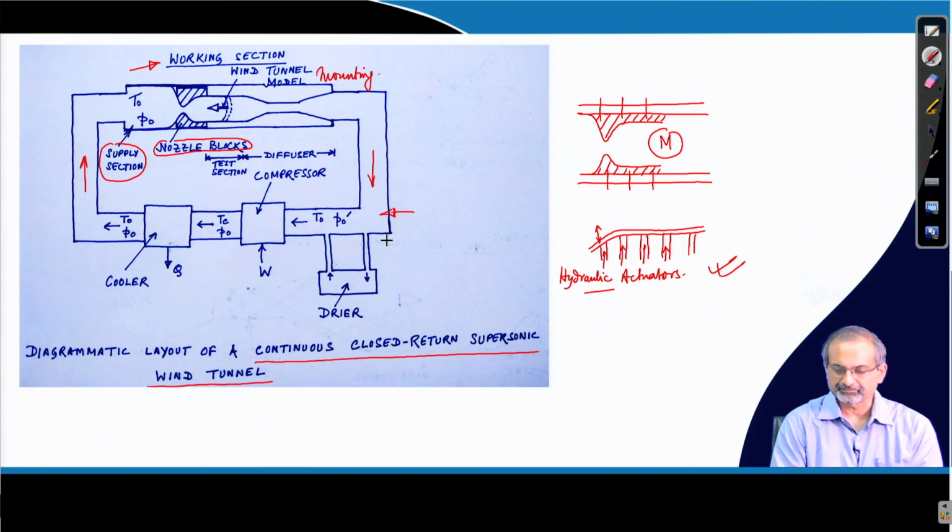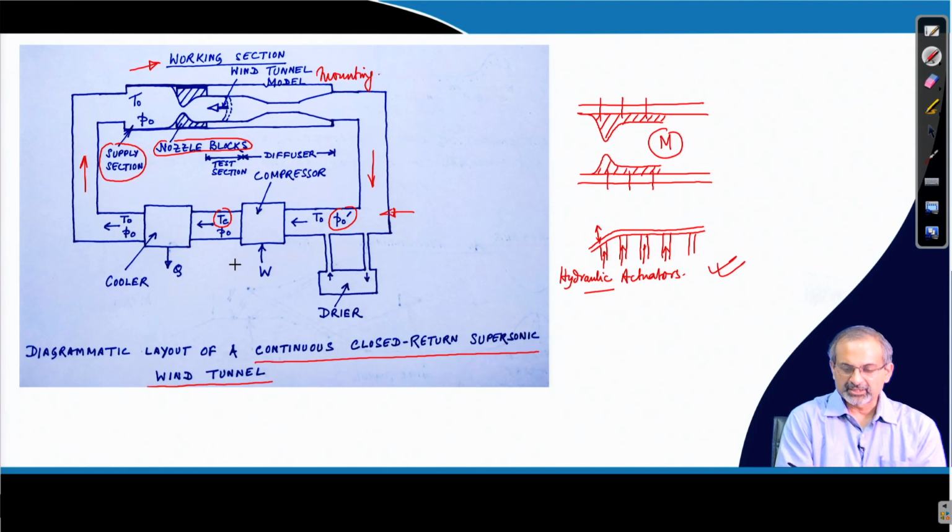And then you can see that after the run the pressure changes, and though the stagnation temperature may not change significantly, once the compressor runs on it, it does work on the gas, the temperature will change. The pressure which had reduced at the end of the run due to irreversibilities is again restored by the compressor, but as the compression occurs, the temperature gets increased, which has to be reduced by passing it through the cooler.